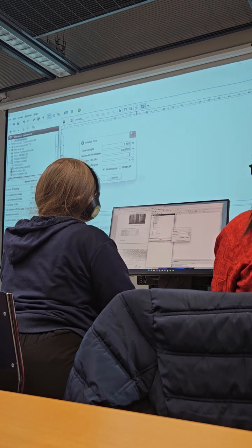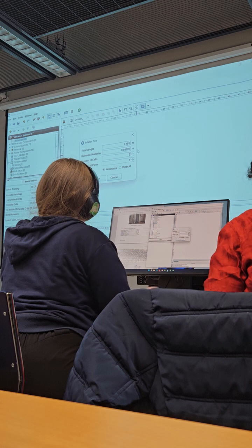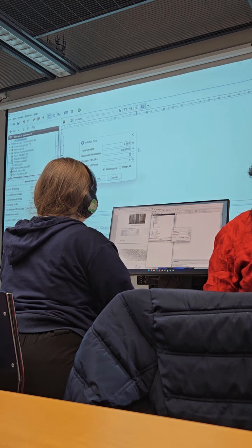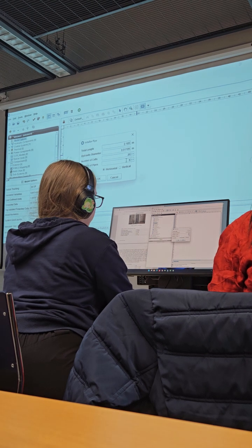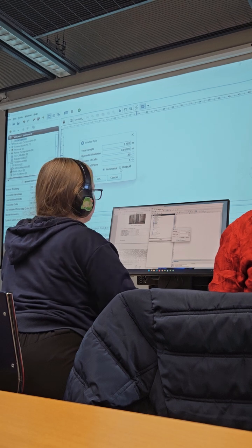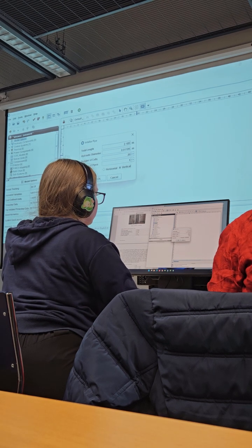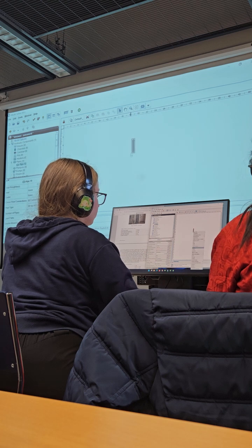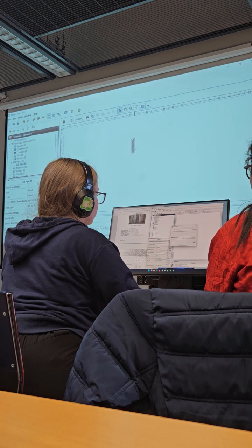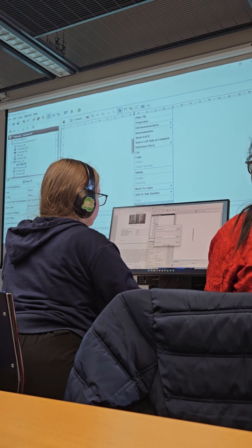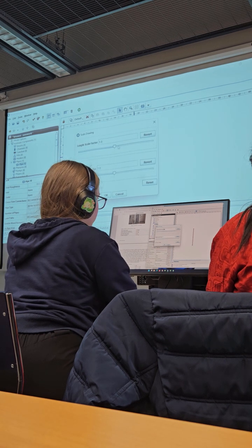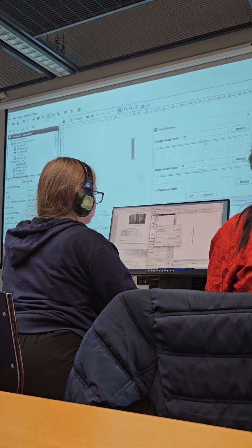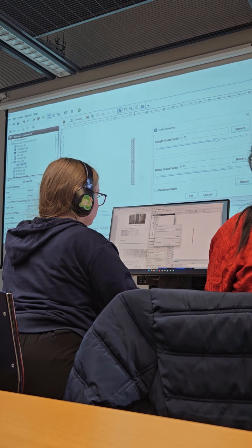Yeah. Okay. So for the number of cells for my simulation, I use 20 cells. We have one pipe and it is a vertical one. So we need to choose the orientation to be vertical and just press OK. It is really small. We need to make it clearer. We can make a scale drawing and just make it a bit longer and wider. 500. Like that.